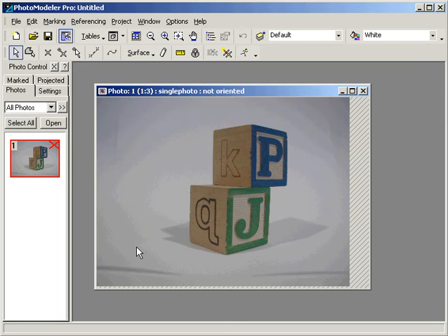We will now begin working with our single photograph. We can solve for focal length in this two-point perspective image, but we need to use constraints. Constraints refer to known information about the object in the photo. Constraints come in two forms in PhotoModeler. One is called simply constraints, the other is called control points. First, we will work with the constraint mode.